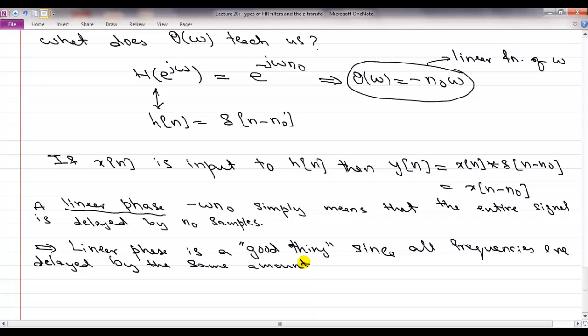Let's again focus on the case of voice. Right? Our voice is not simply made up of frequencies. Like if you take the DFT of my voice and you see that I generate these frequencies, and if you generate any other signal with those frequencies, you are not going to regenerate my voice. Why is that? Because it is not simply the frequencies that are present in my voice, but also their temporal relationship with each other. Whether a low frequency is generated first and a high frequency is generated later, and so forth. Okay? So frequency itself does not give you the timing information. And a linear phase, what it does is it delays all the frequencies by the same amount. So you hear everything as it was initially. And what that does is you have no change in perception at the end.